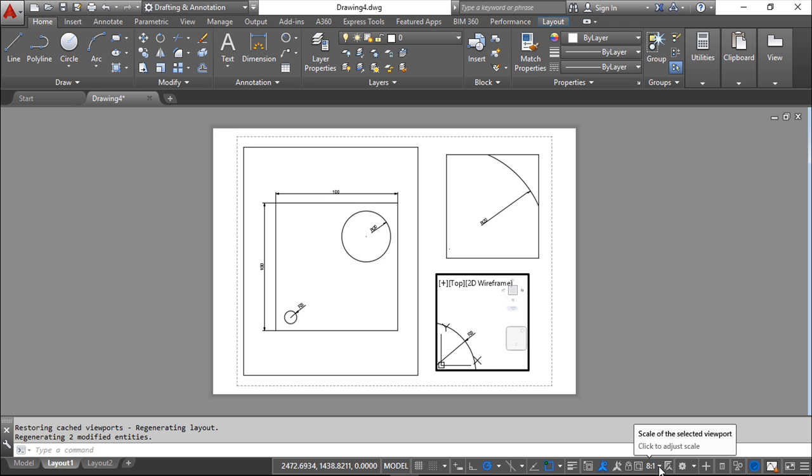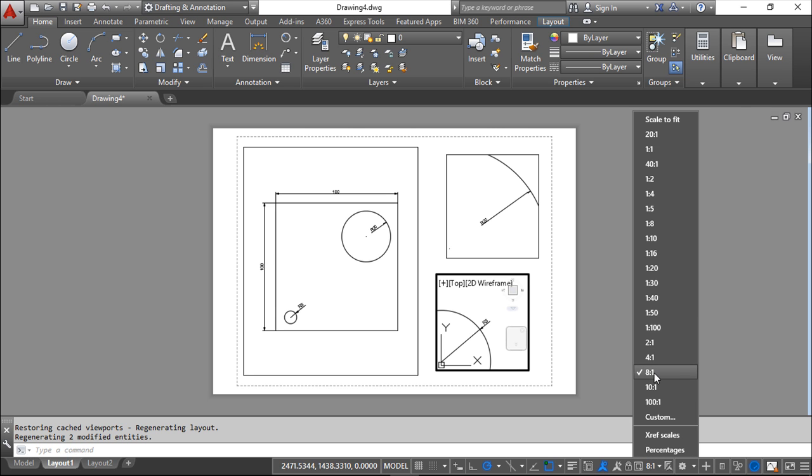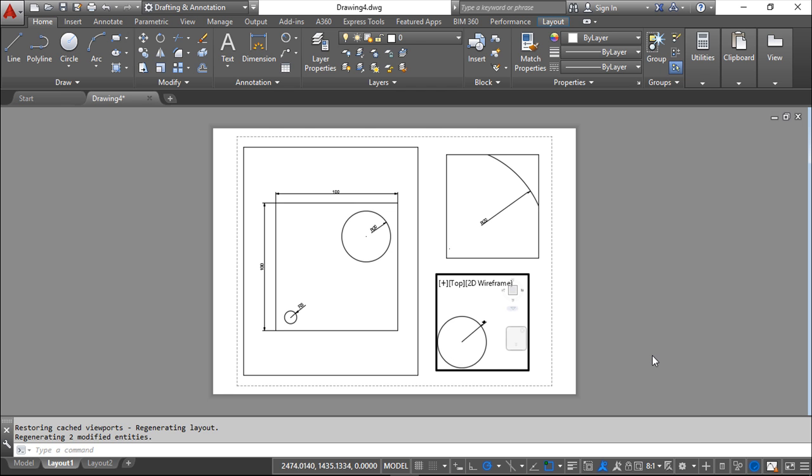When I have the scale equal to the one that is defined and linked to the object, you'll see that the objects with that property assume this functionality already. If I said in this particular case it has scales of 20 and 8:1, if I set here 4, you see that it does not respect anything and will have the standard size or the original size.